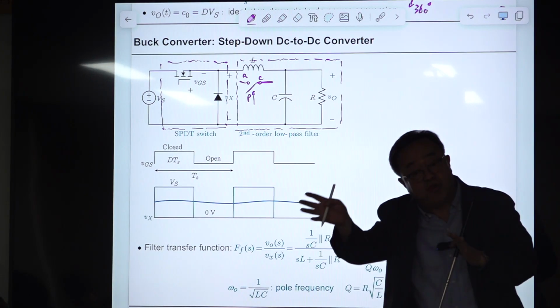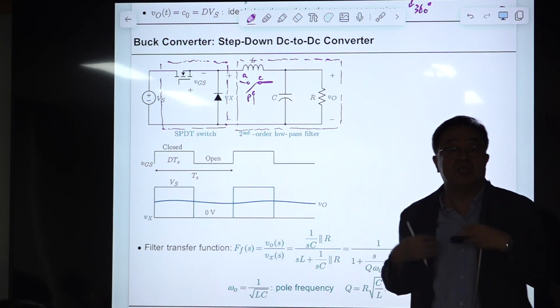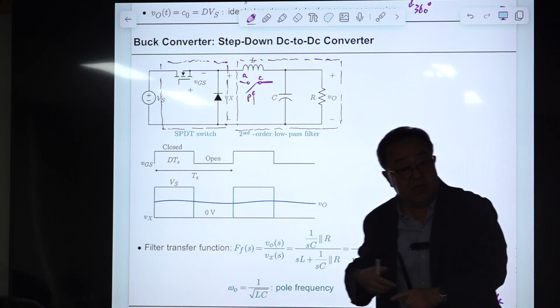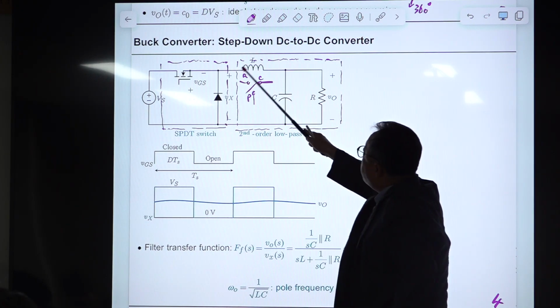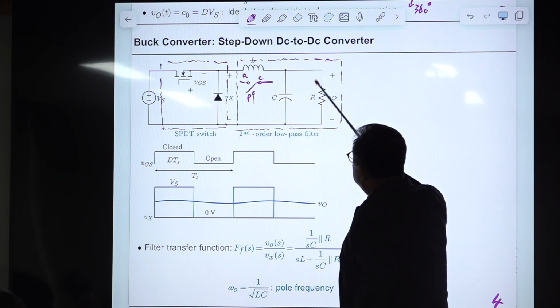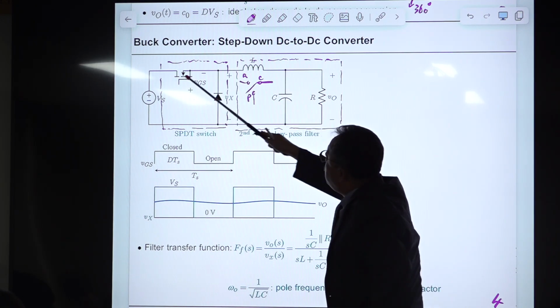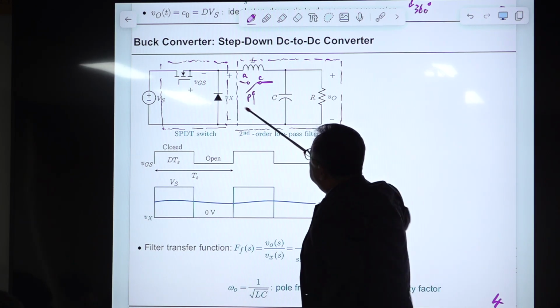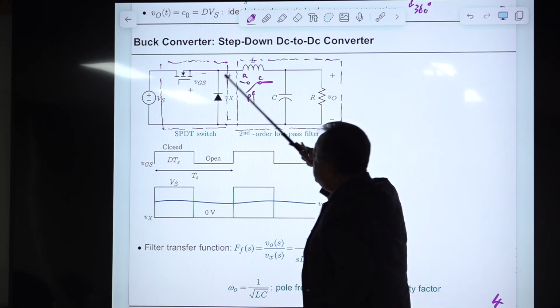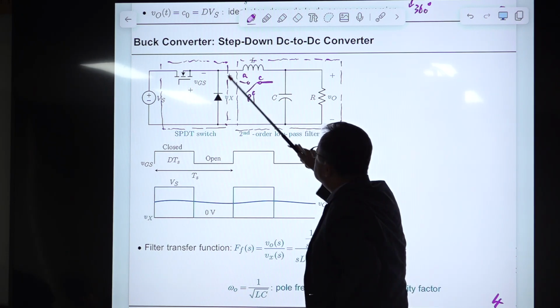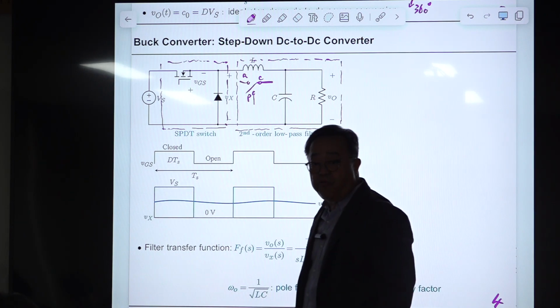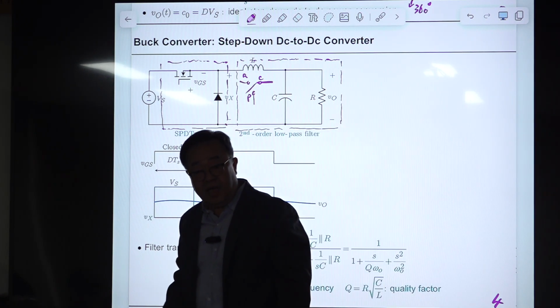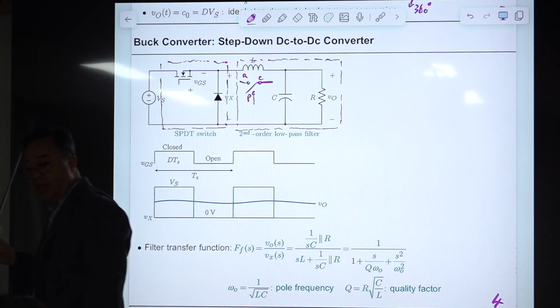There is a way of doing that. The inductor current will do that. So this current is cut. The inductor current goes here, comes back here. There is a low return path. This is off. Then that current turns on this diode and creates this path. It's called the freewheeling path, and that diode is called the freewheeling diode.